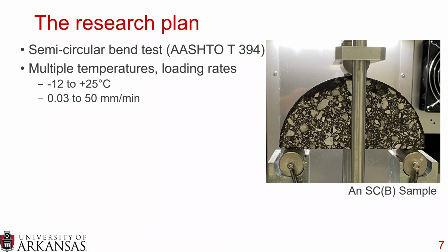It's also used for the Illinois IFIT test. However, the LTRC test is a little different because it changes the notch length. But they all have different testing temperatures, different loading rates. So we wanted to encompass all three of these tests, all three of the loading rates and testing temperatures, to see what would happen when we calculated the fracture energy, because all of those tests, along with the SCB, calculate fracture energy.